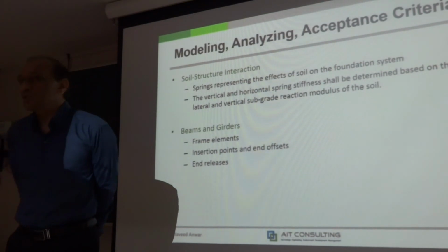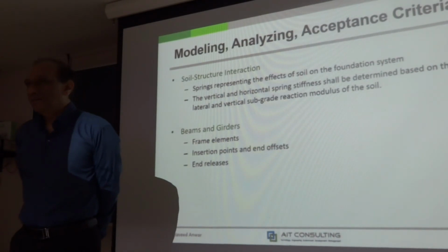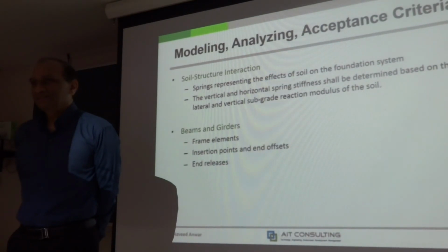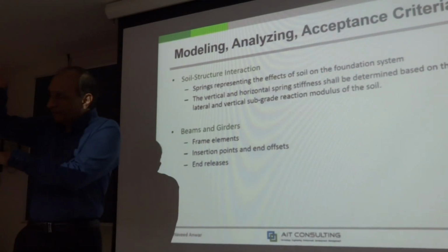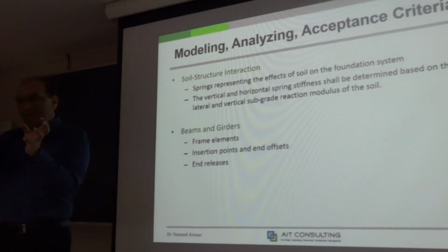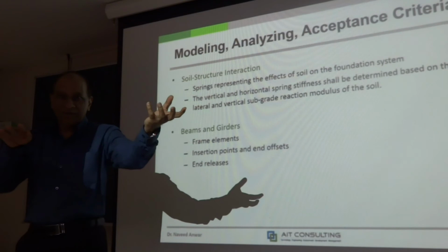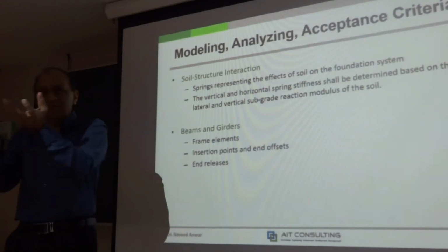What is happening in the real structure? Think about that. Why can't we just follow what is really happening? What is really happening is that the dead load and live load is being applied first, and then that loaded structure is being subjected to earthquake movement. Not independently calculate dead load, live load moments and add to independently calculated earthquake moments and combine them together.